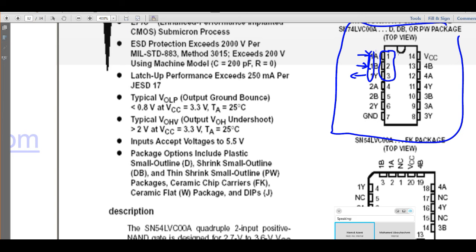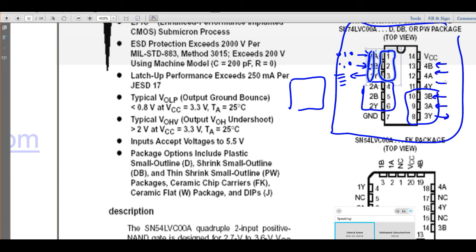In today's lab, we'll give you chips, and you can identify them by just putting 0, 1, 0, 0 combinations in those inputs, and collecting the outputs. Through this truth table, you can create your Boolean expression, and you can identify if it's AND, or NAND, or any other type of gate. Here, this one has one gate, another gate here represented by number 2. Another one by number 3, and you see those are the inputs. This is the output. This is the input. This is the output. So we have four gates inside this chip.